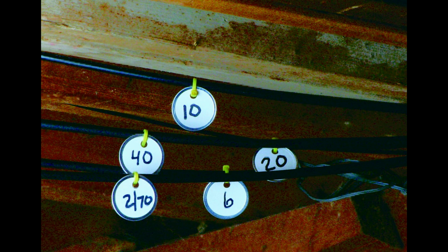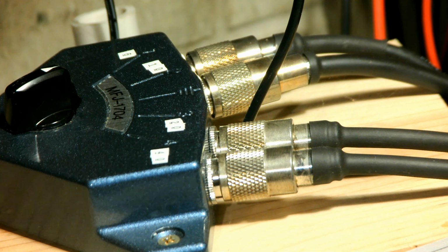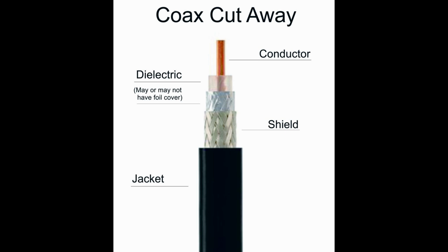Coaxial cables are electrical transmission lines used to pass high radio frequency (RF) signals from one point to another with low signal loss. Coaxial cable has many applications, including phone lines, cable TV, internet, cell boosters, and most importantly amateur radio signals. Coaxial cables come in many sizes and lengths, each designed for specific uses. As you can see from the image, there are four main parts to a coaxial cable. Number 1 is the center conductor. Number 2 is the dielectric insulator. Number 3 is the shield. And it is all protected by number 4, the jacket.